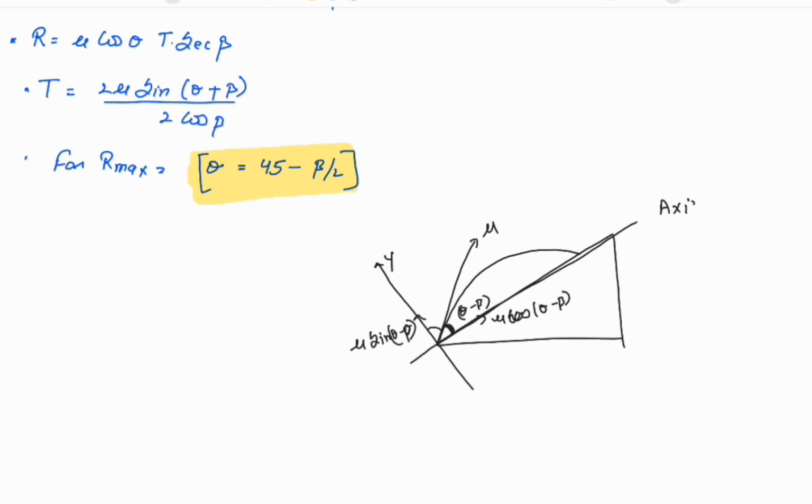Only here in the inclined plane, we are getting the acceleration value for the horizontal. How have we calculated the acceleration value? Like this. This is the inclined plane. Here we have g, and g always works downward. It will have some component along the plane and a component perpendicular to it. This angle is beta. Then this is going to be g cos beta and this is going to be g sin beta.